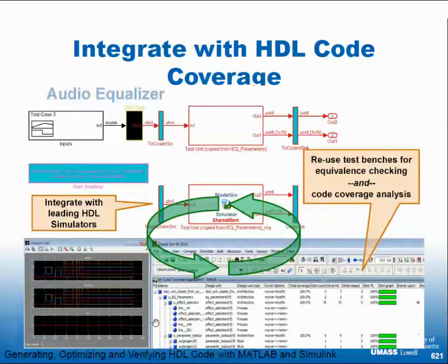So ultimately, this top one right there, that's the sum of the coverage of the whole design. If you click the minus sign here, that would be the only line that was there, and this bar would tell you what the coverage of the design was. But then to debug it, if this comes out to be 56%, you've got some work to do, and then you go down and look at lower parts of the design. That's a graph of it, kind of useless.